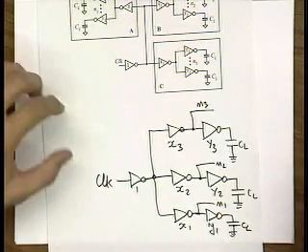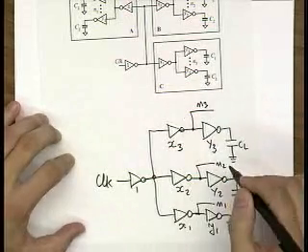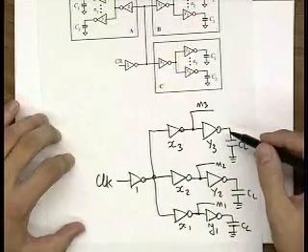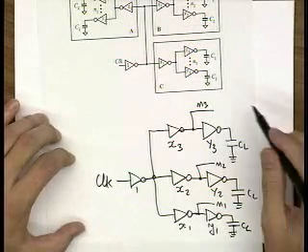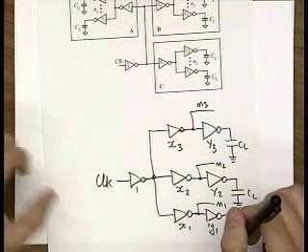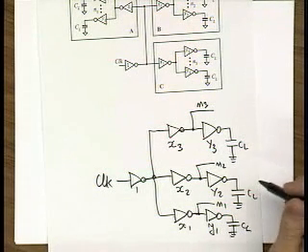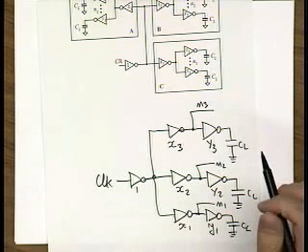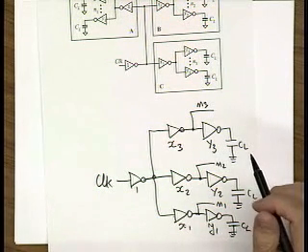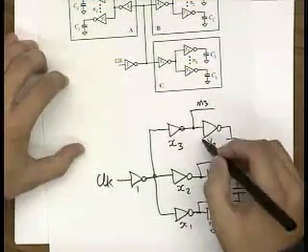Okay, everybody following? Since you have imbalance in the load in each of these branches, because the total load capacitance is different, you are not going to have equal x1, x2, and x3 that will balance your delays. That is the major deviation from the branching theory that we did. I'm going to teach you later in this class that, although that theory was developed at Stanford, I'm not going to say it's wrong, but it holds only under certain conditions, okay? What you actually imply when you apply this branching factor is that you assume that the size of all of these parallel branches is the same.